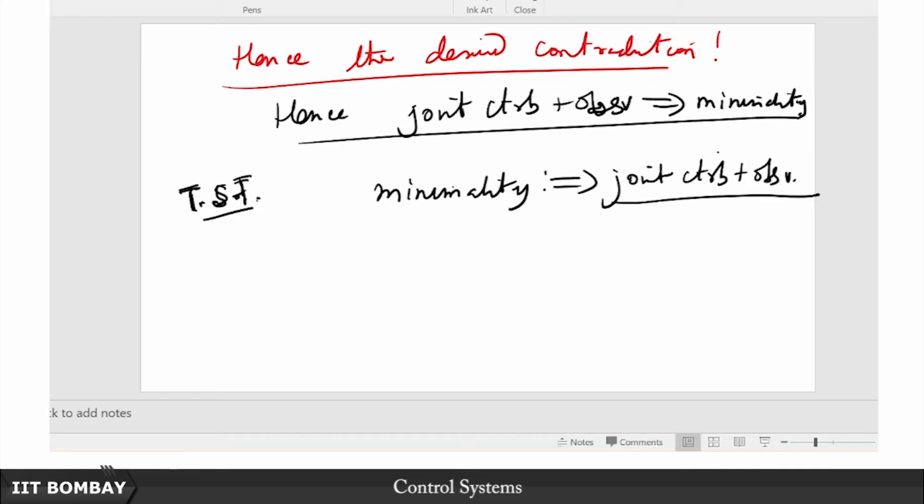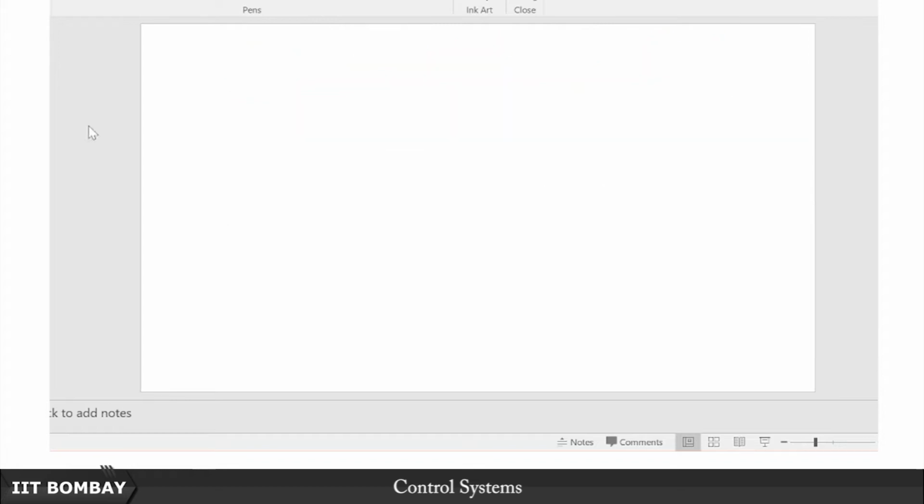If you check the numerator and denominator polynomials and check their GCD, the greatest common divisor, if that greatest common divisor is unity, then you would know that any realization you get to in the state space domain will be jointly controllable and observable. So that is a beautiful thing. And now we are trying to see that if you come up with a minimal transfer function, then from it whatever you derive, you will get that realization as jointly controllable and observable. Sorry, we have not proved it yet, we are yet to prove it. So what we have proved now is that if a state space realization is jointly controllable and observable, then you are basically using the minimum number of integrators that you absolutely need, nothing is redundant. So now we will see the other way around again. So this is a reprise.